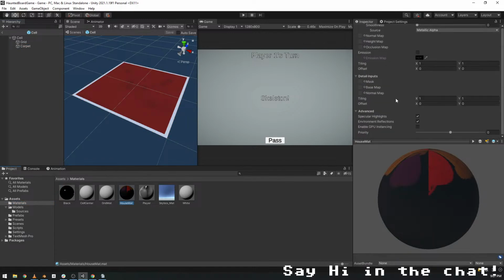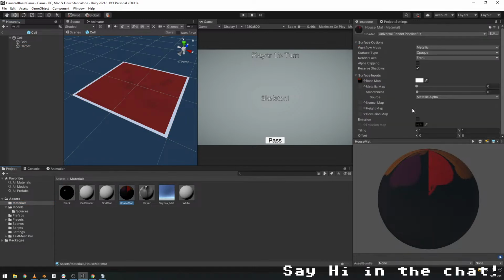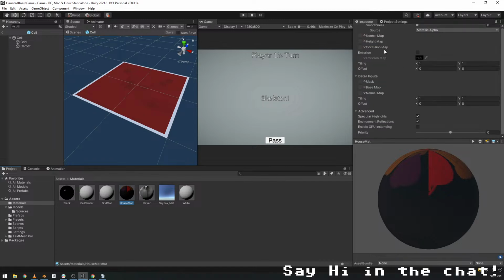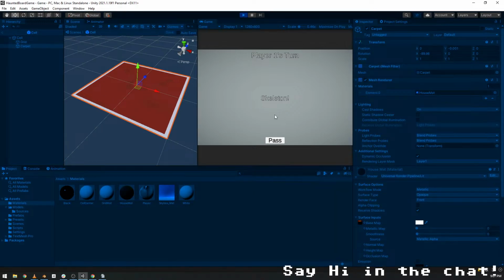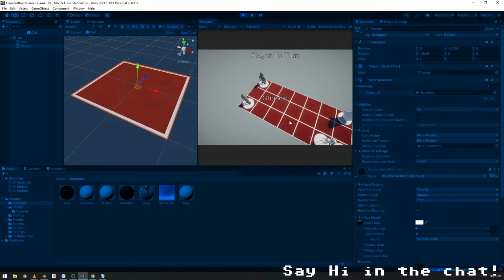Let's see, can we do this in here? So we want it to stop, like, the Z fighting. Do we drop? Yeah, I forget how to do it in here. We're just gonna drop this down. So we're gonna change its Y to -0.001, right? So this is some tiny value lower, so it'll automatically get rendered lower. Hopefully. Maybe. There we go. No more Z fighting.